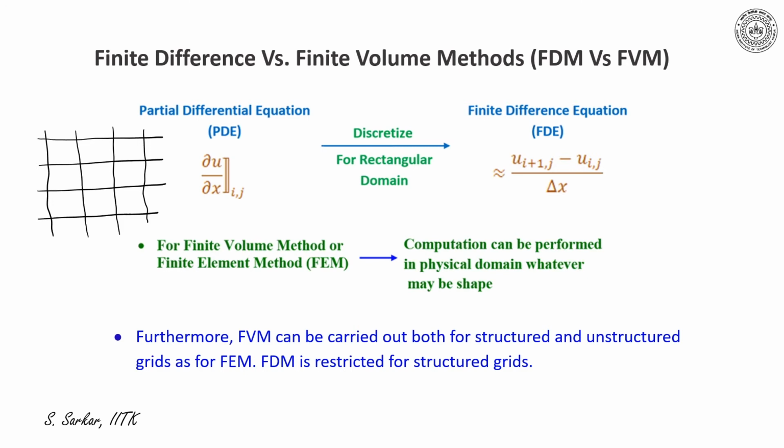I have indicated a cell being a finite volume, and I'm considering this scheme as a cell center. That means at the center of each cell, I will store the variable and update that. So all centers of different cells in the mesh I have indicated by cross.